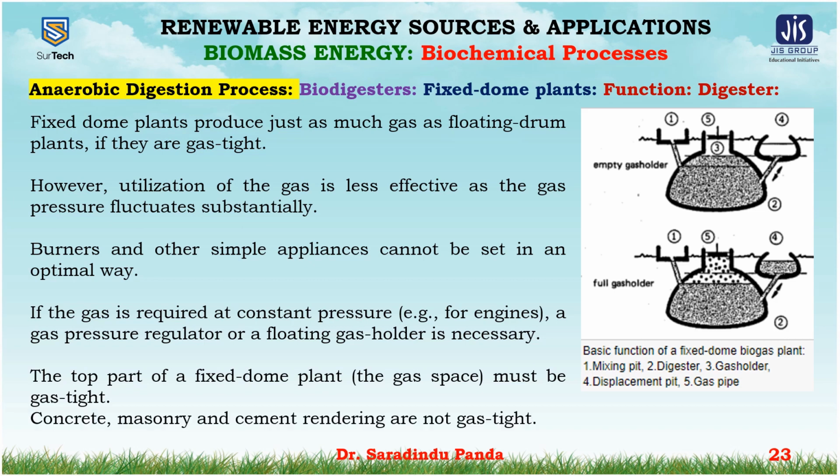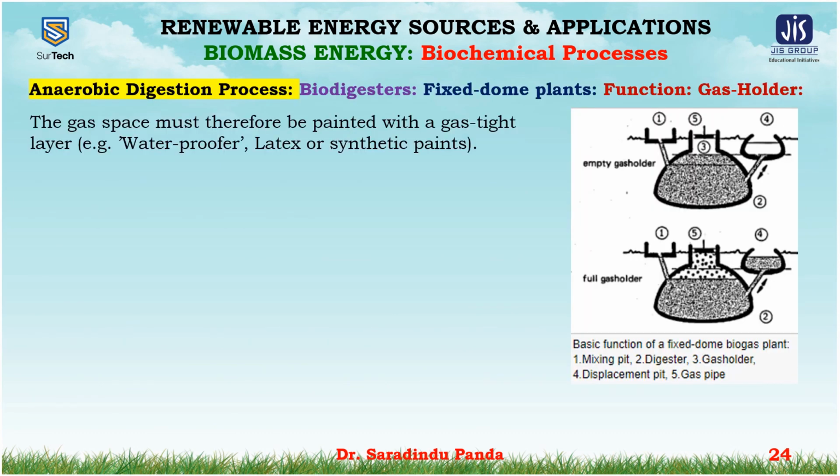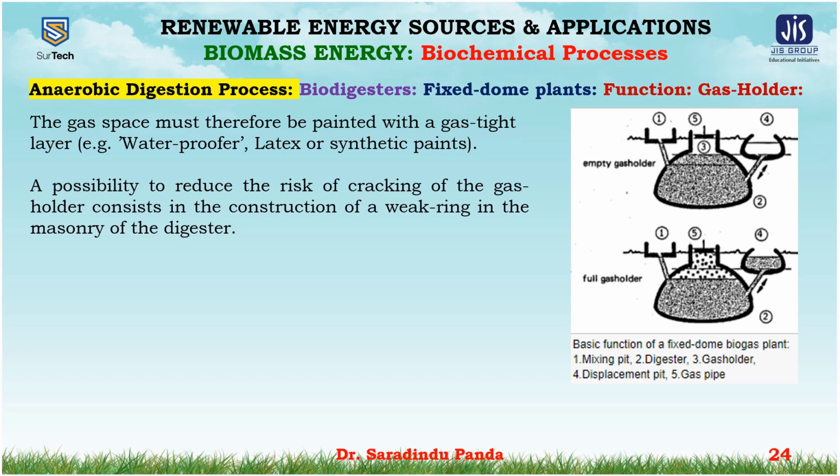Concrete masonry and the cement rendering are not gas tight. The gas space must therefore be painted with a gas tight layer, which should be waterproof. Latex or synthetic paint should be used.